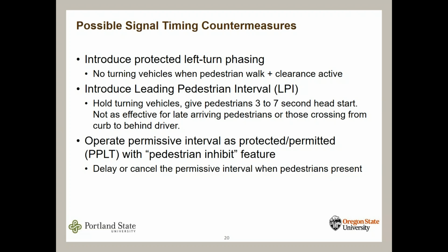So both where the pedestrians are walking and the number of them increases the likelihood that the drivers will notice them. But the LPI might not be as effective for those pedestrians crossing from behind the driver, or those that are arriving late, because this only helps the pedestrians on the start.